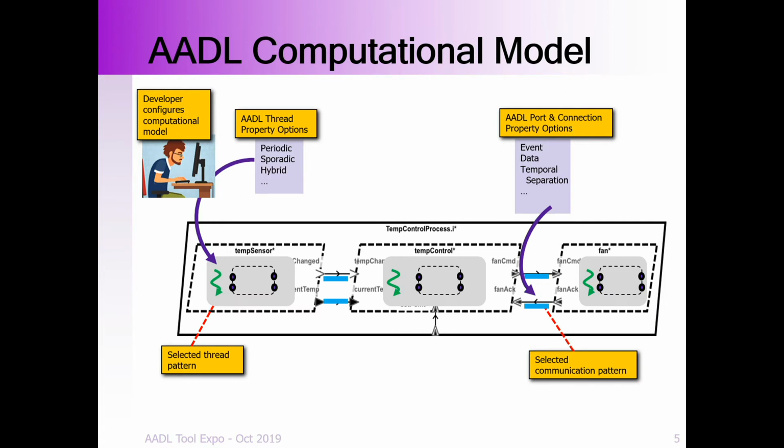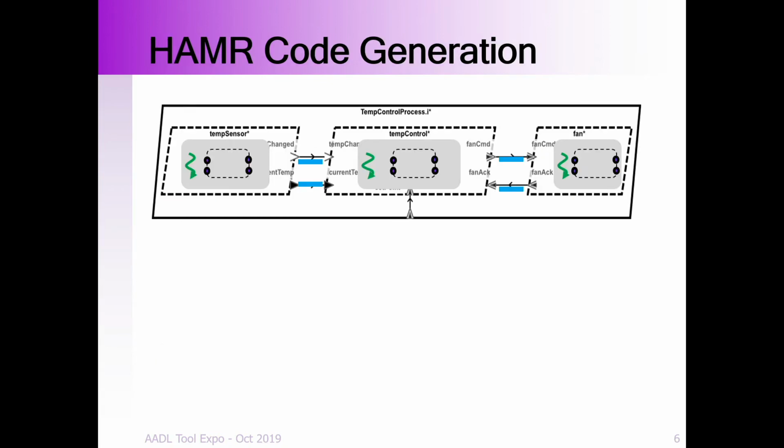And so you can also start to introduce platform elements, like Etienne mentioned in his talk, where you're attaching additional information that says, oh, I may be going down to DDS, for example, or CAN with my communication primitives. So the idea is that, given this type of semantic information, what AADL does in its standard that's very nice is it also says, well, if you're going to interact with these underlying semantics, there's a collection of APIs that you should work with. And the code generation framework can implement the code however it wants, because you're going to be working with those APIs and you're going to be isolated from the distinctions between platforms for this various code generation.